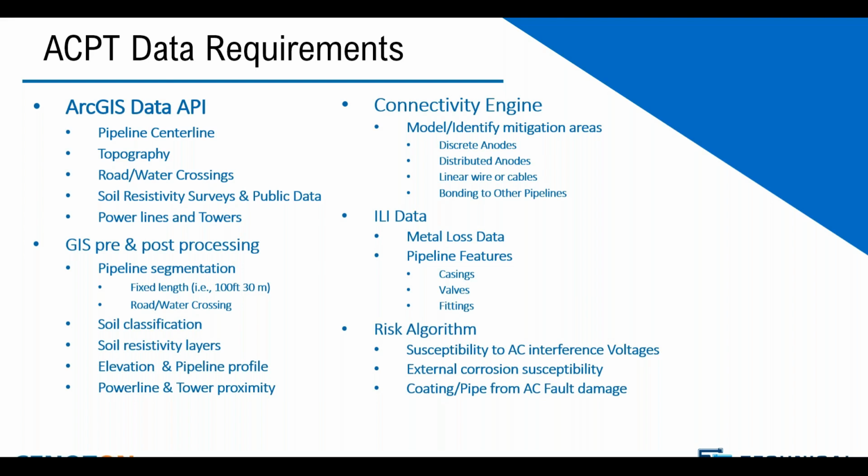We also host ILI data, and this would be the raw data coming from the tool or from the vendor reports. We import the data. It's a completely agnostic import process where we do quality control to make sure the data makes sense. We'll do the linear referencing on the centerlines where we need to if we don't have IMU data. And we can even do run-to-run comparisons for short-term and long-term corrosion growth rates. And of course, through the data, we can identify where all our welds and casings and valves and other critical features are located.